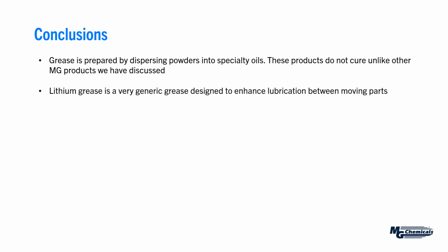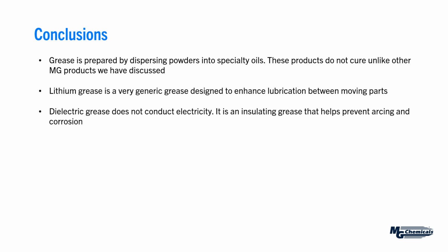We talked about lithium grease. It's a very generic grease that you've probably seen before, and it's simply designed to enhance lubrication between moving parts. Dielectric grease does not conduct electricity, it is electrically isolating, and that's meant to prevent arcing and corrosion because it is very hydrophobic.